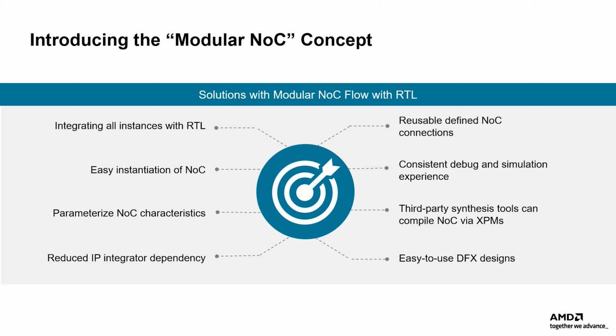So, with all these solutions with the modular NoC and new design entry flow, the utilization of the NoC supporting dynamic function exchange will be easier to use, allowing for traditional top-level RTL flows with reconfigurable modules. Finally, there will be minimum impact on existing BDs, simulation, debug, and XSA generation flows.